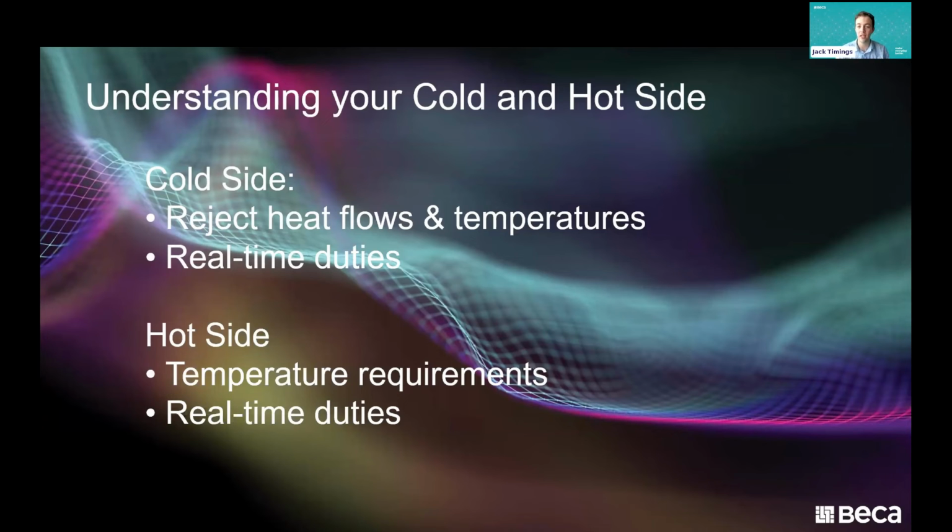Not an uncommon thing to see in the food and beverage world, but until we had put some temporary metering on the system, we didn't know that the flow rate, for example, in the cooling water recirculation loop hadn't changed, which meant that we were rejecting water to a cooling tower and bringing it back into the process with a delta T of 1 to 2 degrees instead of 5 to 6, what the system was designed for. So before we even thought about doing the heat pump, we spent a bit of time getting that refrigeration system working properly again.